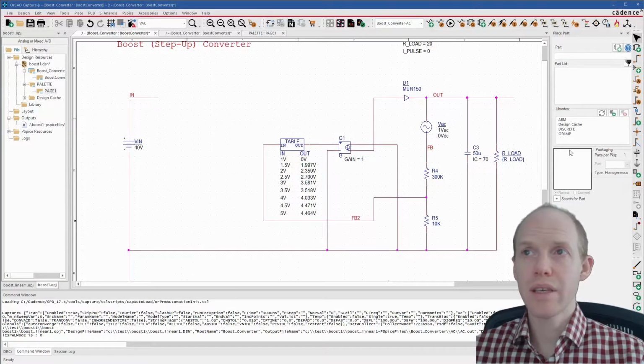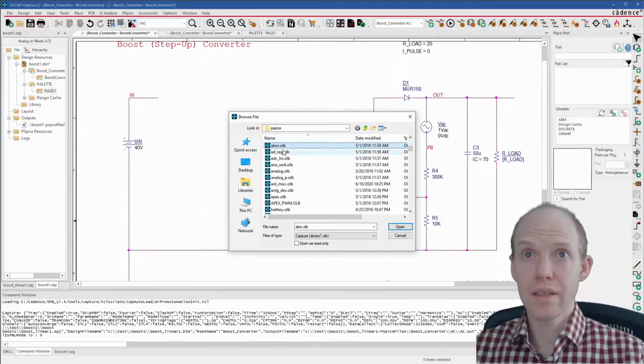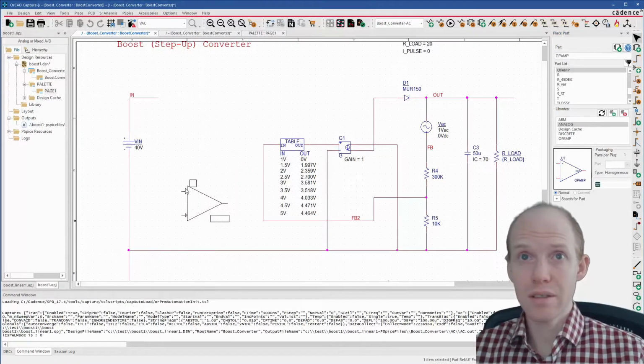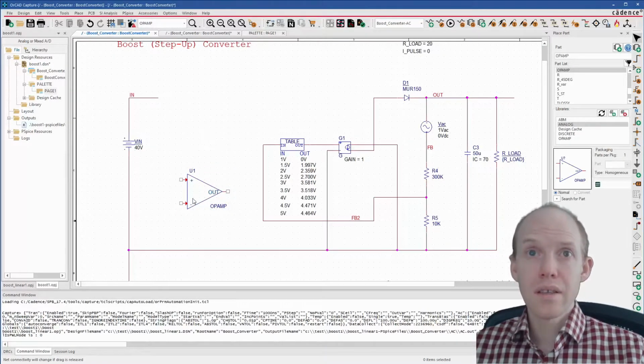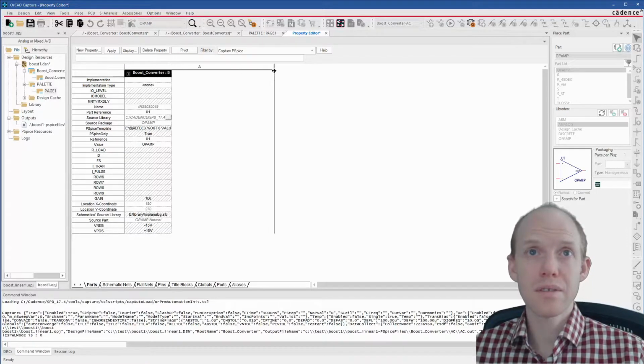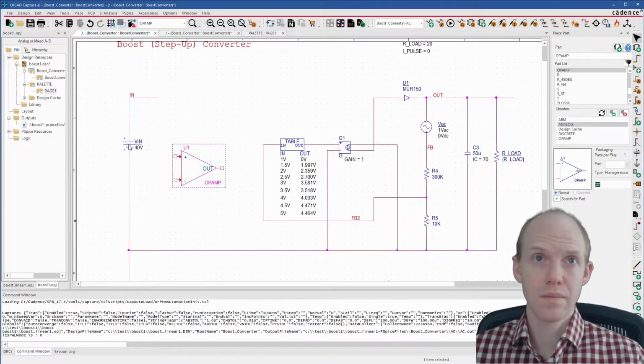So to add that back in, we need an op amp, and let's just do the analog library, and we'll try this op amp here. Press O. And this is just a controlled source, so it's a super ideal op amp. We'll give it a reference of 2.5 volts and do that compensation, just like in the other schematic.